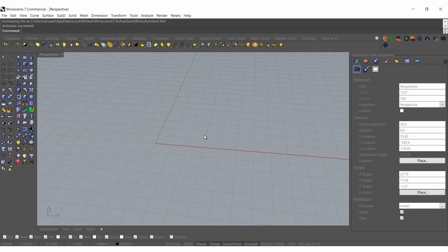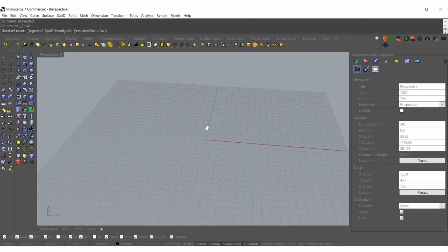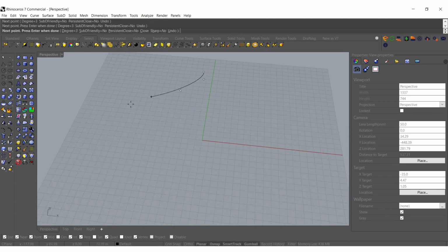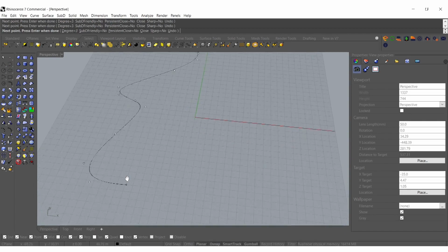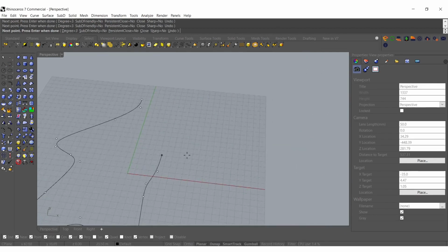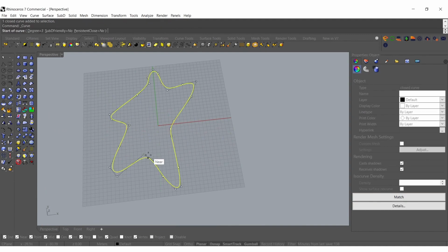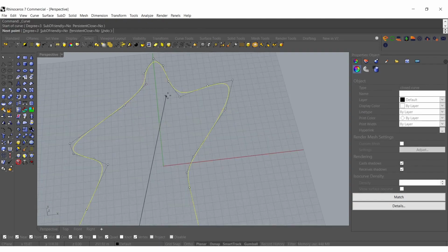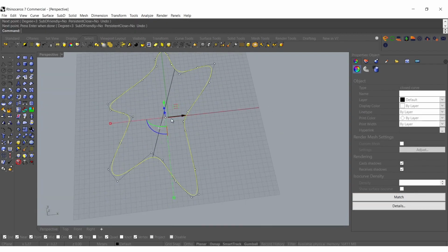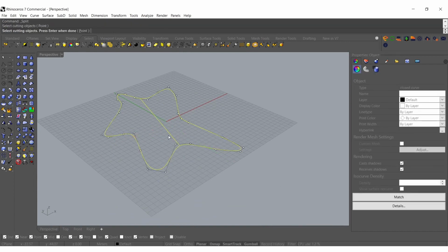I'm thinking in my mind, we're going to make these canopy systems overlooking a lake type of thing. So I'm just going to draw some random shape here that I think could be potentially interesting. Something like this. Okay, and then I'm going to split it down the middle using another curve. So we'll just take the same curve. What we're doing is setting ourselves up for a loft.